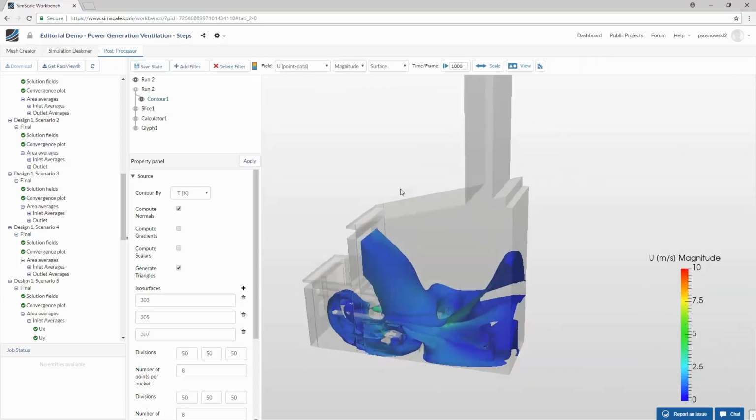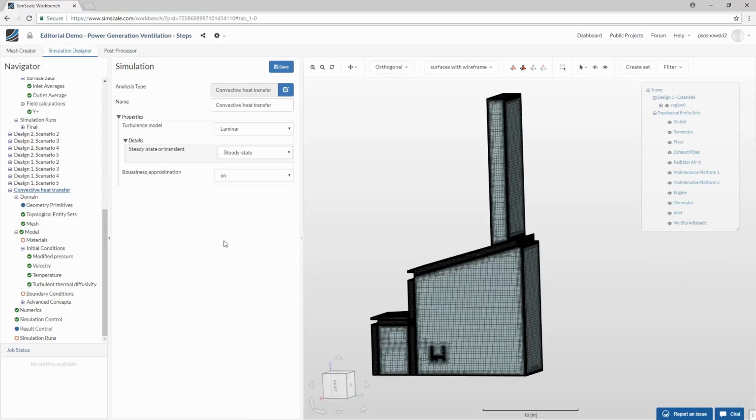Okay, there's another question. What is the role of y plus in this simulation? What values should we look for in this case? Yes, so y plus, the non-dimensional wall distance, defines how well we are resolving the flow next to the wall. For the models that we're using over here, you would try to get your y plus values at any surface that is not moving to be in a range between 30 and 200. This is the target. Of course, if you have several cells that are not matching that, it's okay, but for more, you would have to change it.